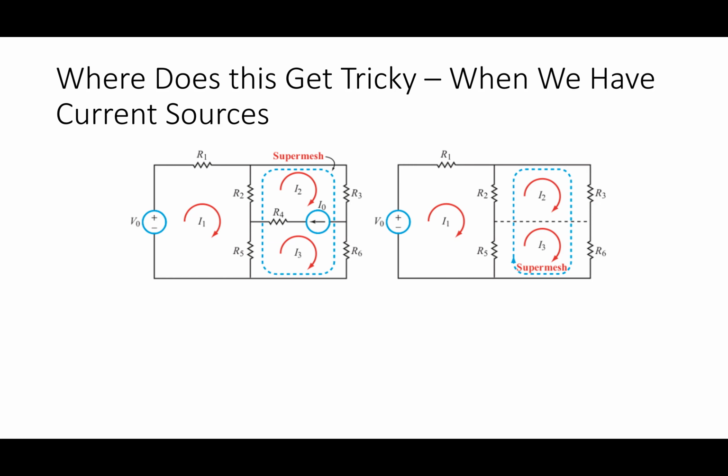Why is it a problem? What makes that a problem? Somebody other than Stephen. Because one of those nodes isn't your reference node. Well, yes, that's problematic, but the real issue is when I'm doing the nodal method, you can't find the current through it. I'm solving for currents when I do that, and I don't have any way to find out the current.